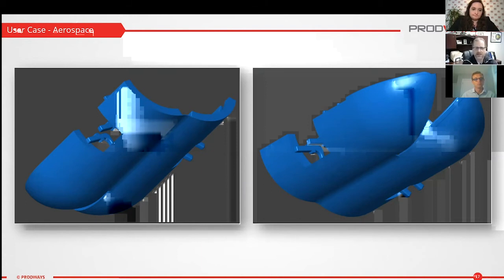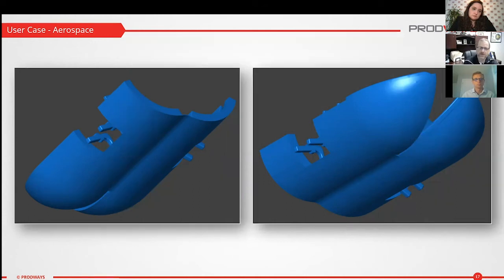You'll see this is a front isometric and a rear isometric view. You'll see the two halves in the middle have a very thin section. That's a live hinge. So these two halves can flex. So there, we're using the capability of a flexible material, but yet it's very durable. So we have a live hinge included here, and that is a preloaded angle. This part was printed in multiple iterations, and we started to understand how that material flexes in that live hinge. So we're using the ability to heat stake, the ability for it to flex.